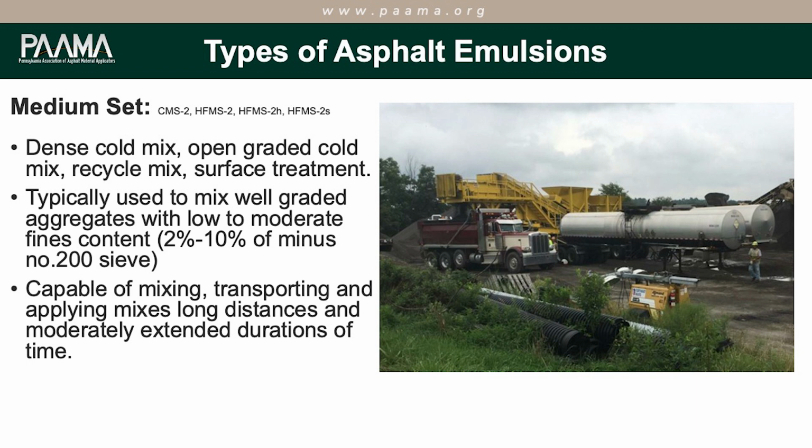Medium sets are typically used to mix well-graded aggregates with low to moderate fines content, so 2 to 10% of the minus 200 sieve. This is capable of mixing, transporting, and applying mixes long distances and moderately extended durations of time. So you have your pug, and if you've got 45 minutes to drive down the road before you're paving it, it shouldn't be an issue. It's not going to come out in a cube out of the back of the dump truck.